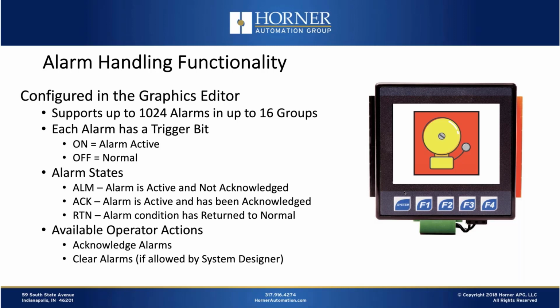Now each alarm has a trigger bit, and when that trigger bit is on, the alarm is active. When it's off, the alarm is normal. And there are multiple alarm states to deal with alarm conditions. When the alarm trigger bit is active and not acknowledged, the state is said to be in alarm, and that's abbreviated with ALM in the case of our product. When the alarm is active but has been acknowledged by the operator or maybe by somebody remotely, then we call that an acknowledged status, ACK.